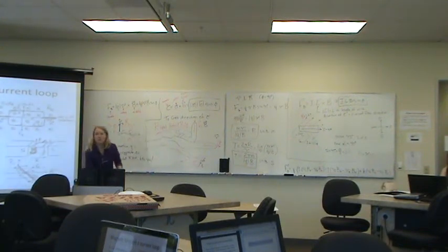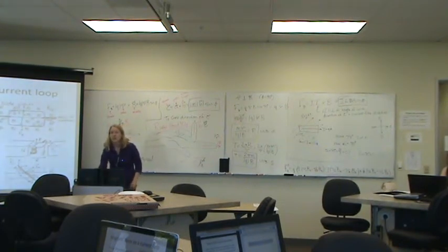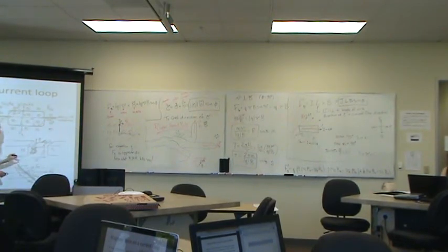Now, is the coil rotating, or the B field? You're putting the B field as a magnet going in the center of it? Yeah, so let's assume in this instance that our magnet is fixed. It doesn't move. And our loop of wire is on a little stand so that it can rotate, so it experiences the force. Of course, you can always flip this and have the magnet be the one that rotates and have this be fixed. That's harder because then you need variable current through your wire. But this one you can use a fixed current and a fixed magnet and it'll cause this loop to rotate.